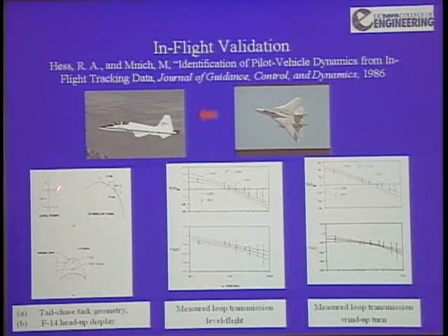And he said, well, look, when I'm behind the T-38, I'm getting bumped around by the wake from the airplane. And it doesn't do me any good to try to track better. I'm just getting bumped around. When I do the 3G turn, the wake is getting blown by me. It's very nice, steady air, so I can track more aggressively. And that's what you're seeing here. Okay, a higher crossover frequency means a higher closed-loop bandwidth.